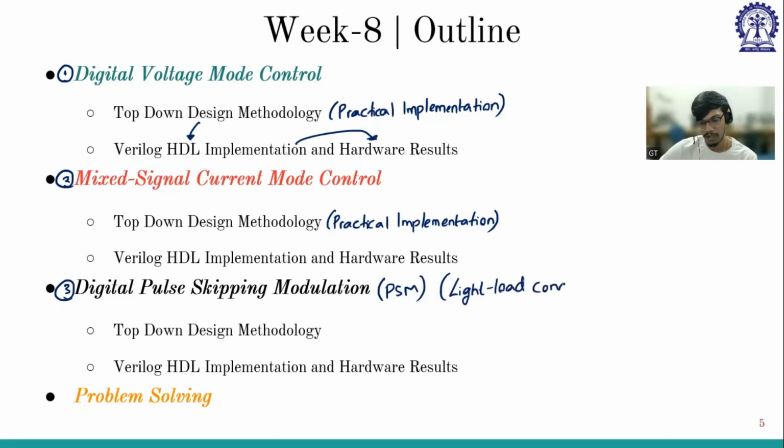The converter is operated at very light load. So let me change the color. Say the ripple is more than the average, and we don't want the current to cross negative, so we use something like this: a charge pulse and a skip pulse. This is to reduce the RMS, which will again reduce the losses. So for loss reduction, we are going for the DCM operation mode, and one such DCM operation is PSM.